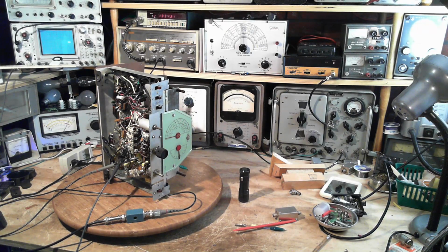I've got two places I'm looking at the signal in the radio. With the SDR, which you can't see right now, I'm looking at the signal right as it comes out of the mixer tube. And then with the oscilloscope, I'll be looking at the signal that's coming out of the IF. That's the idea here. Let me change my display, my screen, your view, and we'll get started.